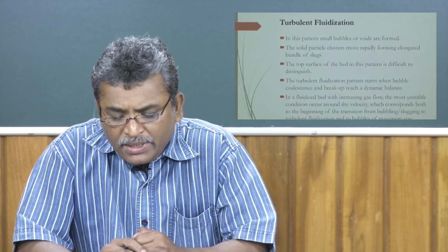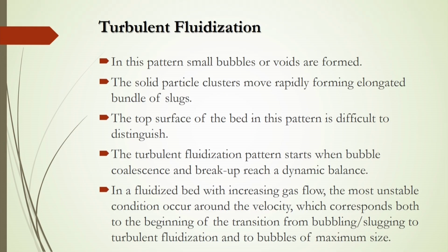The top surface of the bed in this flow pattern is very difficult to distinguish, because of the unstable condition of this turbulent fluidization. At the same time, solid and gas both will be flowing in such a way that the particle-fluid interaction will be higher, because of which you will not get a particular shape of the surface inside the bed, and it will be very unstable in this case.